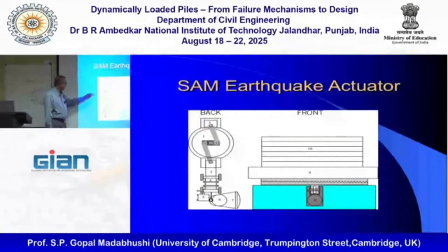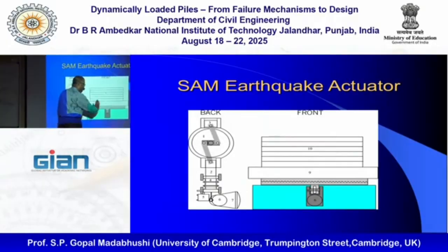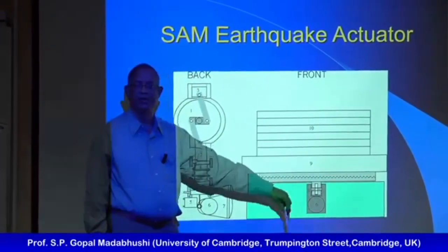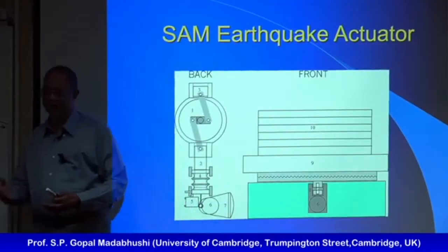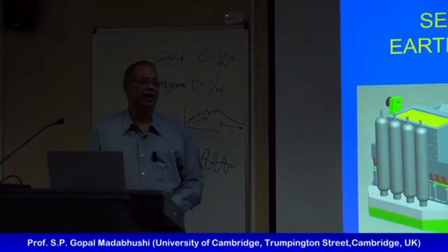So all it is, as I said, is a set of flywheels. We oscillate the reciprocating rod. You run this motor. It's like the old choo-choo train, steam engine, right? So you convert rotary motion into reciprocating motion, and the clutch engages the rod. It's very straightforward. Once this is twisted, this twist here makes the table shake back and forth. And because I can adjust the pivoting distance between here and here by using a three-phase motor, I can get earthquakes of different amplitudes as well. That is the cheap and cheerful earthquake actuator.